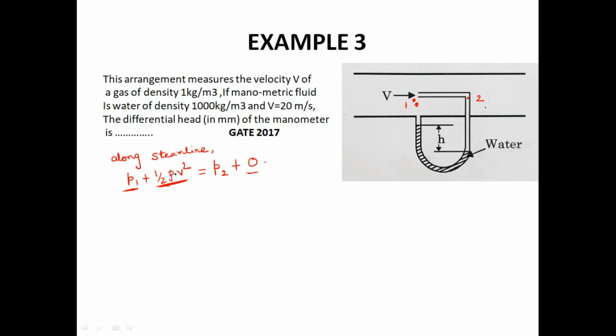So the total velocity plus initial velocity. This pressure is known as the static pressure. And this is the dynamic pressure. The static plus dynamic, whatever pressure we are getting here, is named the stagnation pressure, because we make the fluid stagnant here.